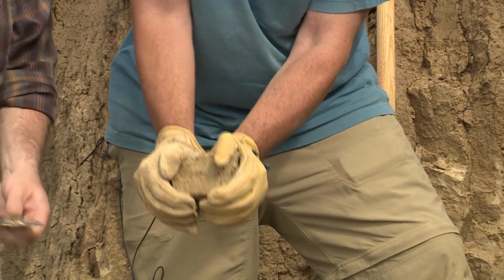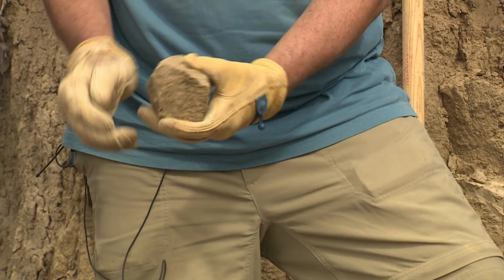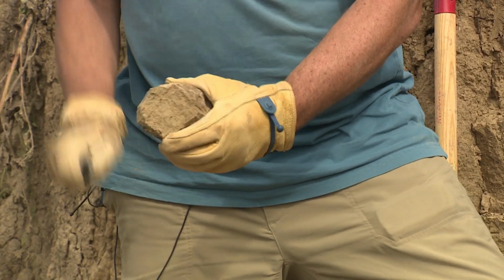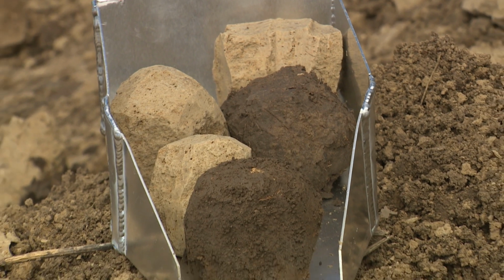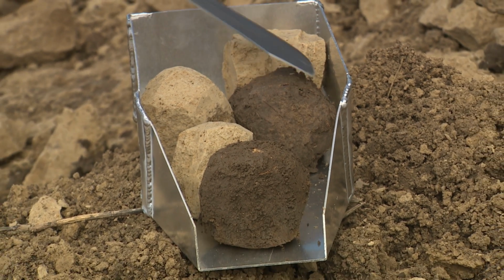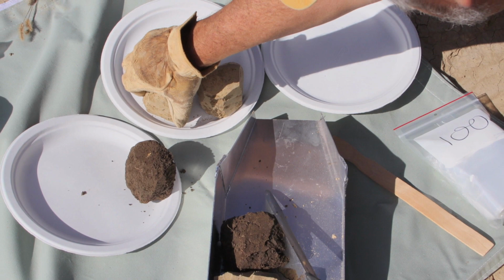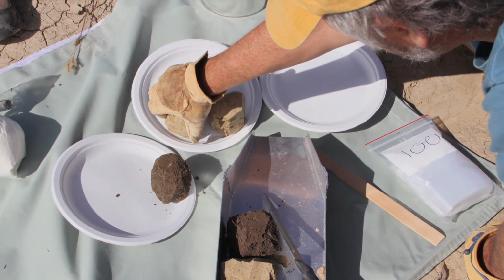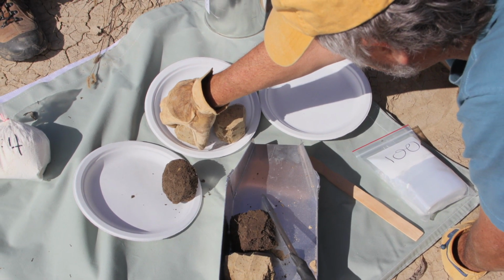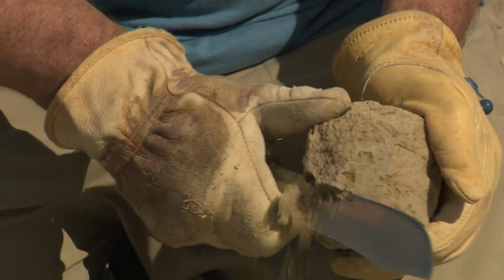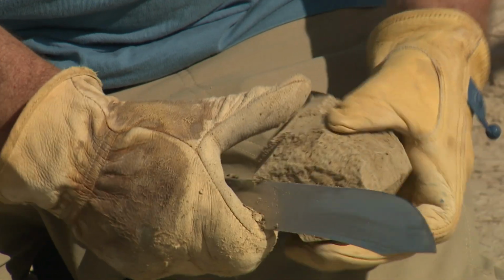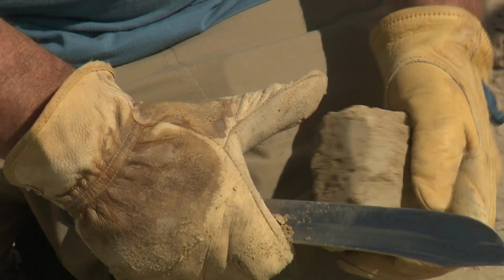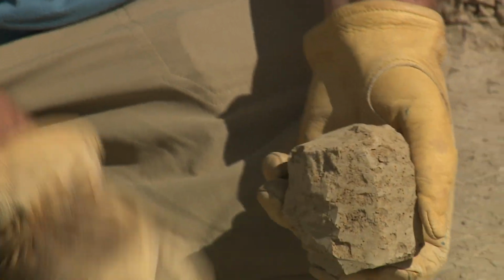Now that we've extracted our clods from the soil pit or the soil face, we typically transport them nearby to a preparation area where they will be prepared and secured to stabilize them for shipment to the lab for subsequent analysis. The process involves taking the individual clods and first trimming each one down to an appropriate final size for dipping and then shipping. We typically sample, extract, and cut them a little oversized so that they can be trimmed down a little bit at the final stage.